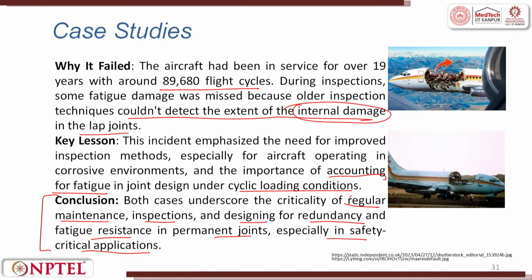So, all the testing that we do is for a period, and for this period this would work. So, it is important to have regular maintenance whenever we are talking about any joints, whether permanent or temporary. Permanent joints would have a maintenance frequency lower than that of temporary joints. Temporary joints could loosen with small vibrations even.